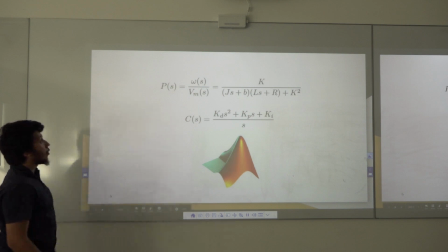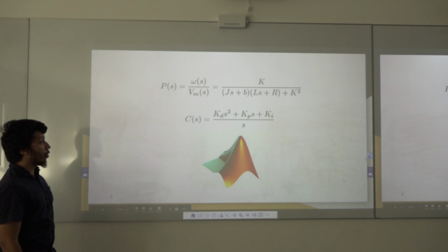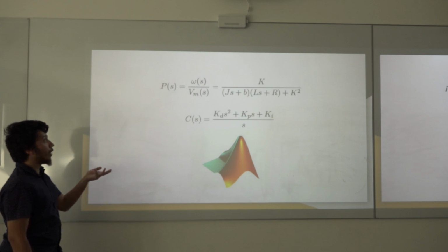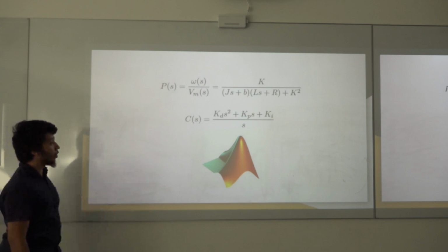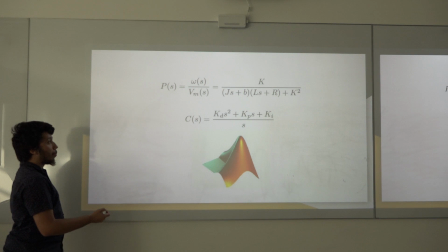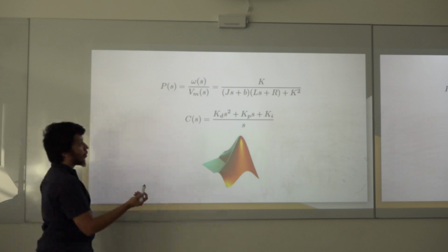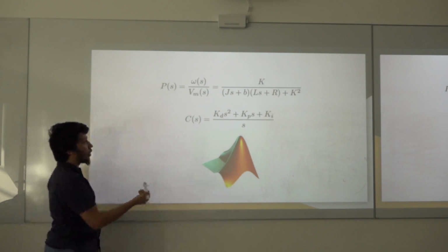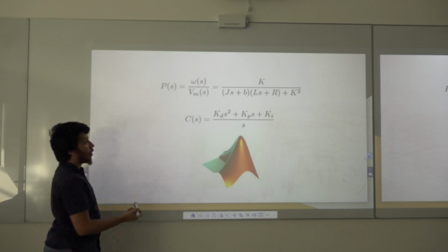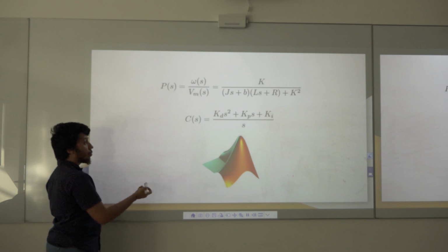To continue on the modeling, the control system that we intend on using uses the motor as the plant. This transfer function that we have on top describes the angular velocity to voltage transfer function of a DC motor. All these parameters are dependent on the motor, and the motor that we used is an example motor provided by MATLAB in an example. The parameters are also adjusted to account for the weight of the antenna, and all of it is determined in MATLAB and using our system blocks.